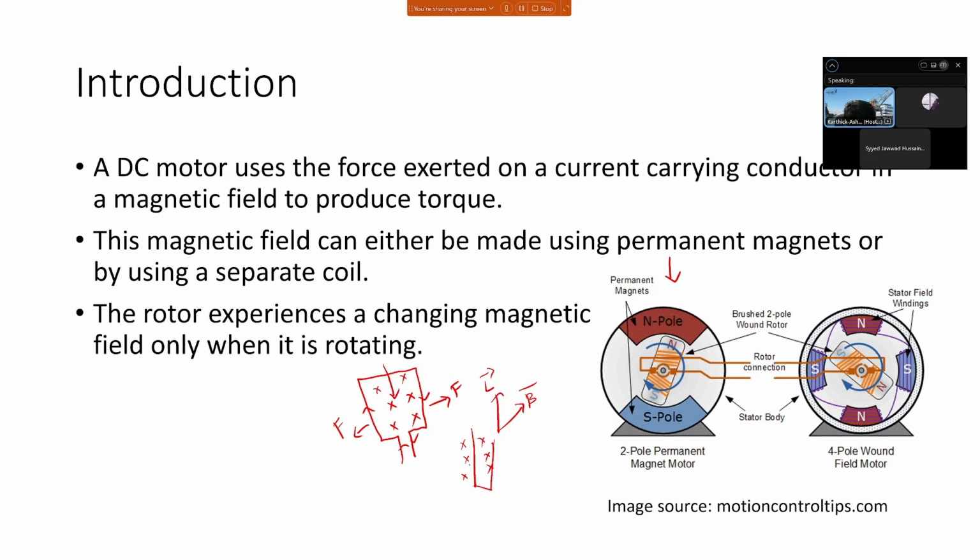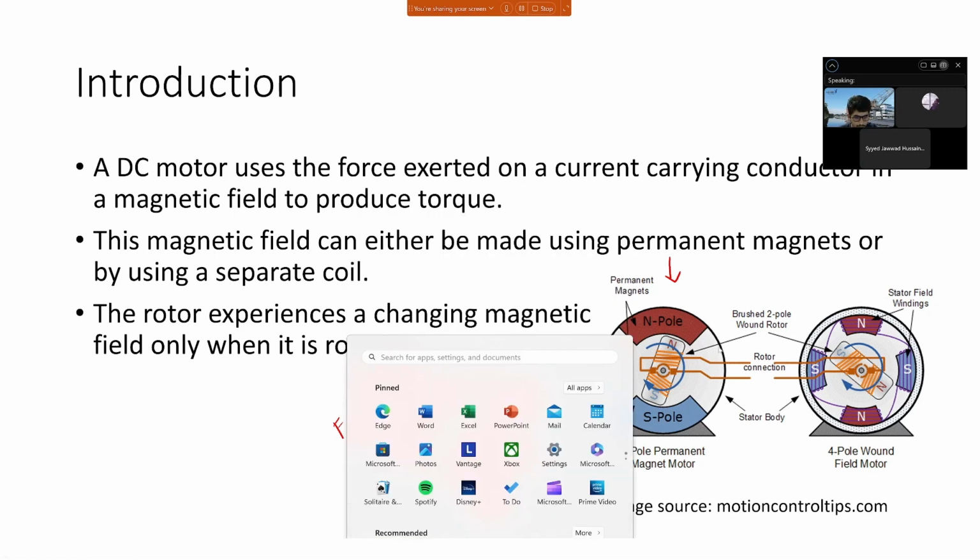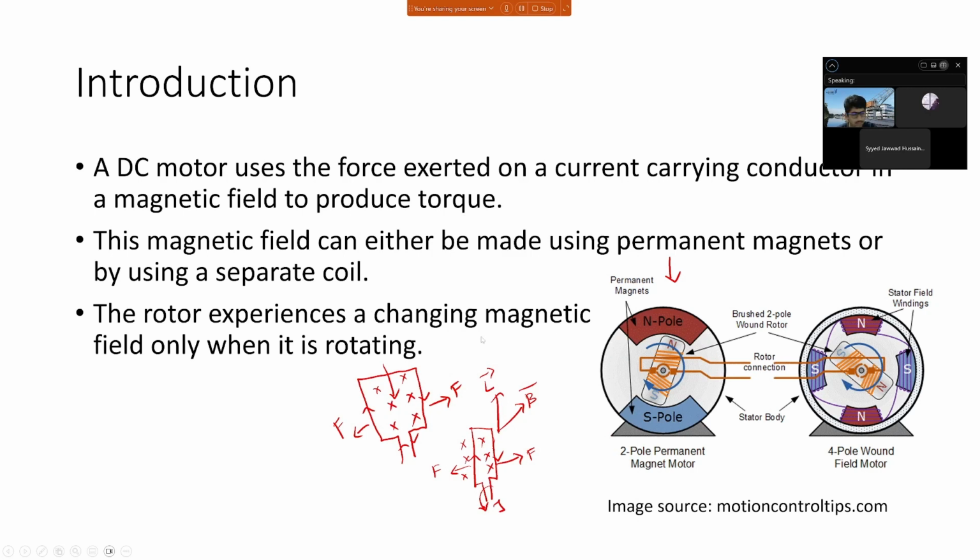Okay, I made a small mistake. So let's do it there. The upper wire is in that direction, lower is in this direction. Left hand rule for motors. Current is upwards, field into the plane. So then you have force to the left. If you do it for the lower wire, it will be force to the right, and that is creating a net torque. Got it? So apologies for my confusion.